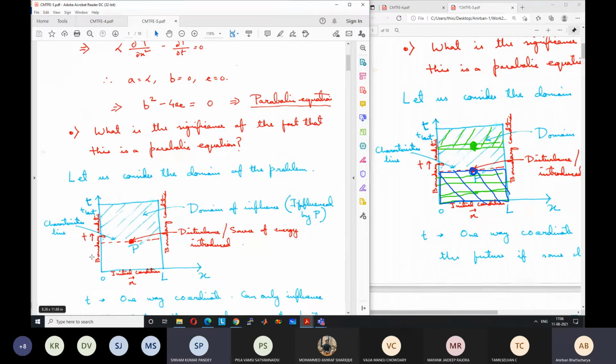Sir, the direction in which the flow is occurring will be the domain of influence. Yes, from that point. And before that point, the upstream side from which the flow is coming is the domain of dependence. So any change that is occurring on the upstream side will influence that point, right? So if I introduce another drop of ink beforehand, that will influence that point. So that is the domain of dependence.